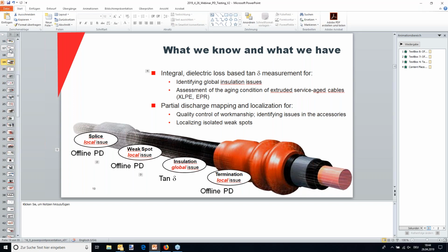Is there an end, a maximum? Yes, there is, but that also depends on the cable construction, because remember, it's TDR-like localization. So if you have a cable with a high attenuation, the typical pulse doesn't go very far. So then you have to calibrate with higher pulses. Instead of calibrating typically with 1 nanocoulomb, that's 1,000 pico, that's a very common calibration setting.